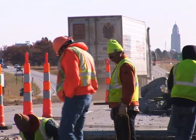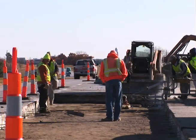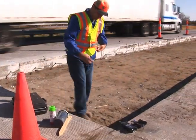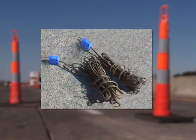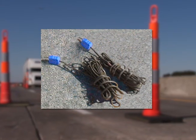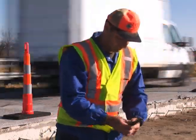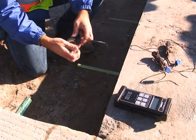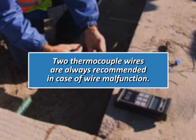The first step is to determine where the thermocouple wires and connectors will be placed. It is recommended that you place your wires at the beginning of the day's placement. It is suggested to set up as far away from traffic and construction equipment as possible. It is also recommended to install 2 thermocouple wires to monitor the concrete placement. Both wires may be installed at the same location at the beginning of the day's placement. Another option is to place 1 wire at the beginning and 1 at the end of the day's placement. 2 thermocouple wires are always recommended in case of wire malfunction.